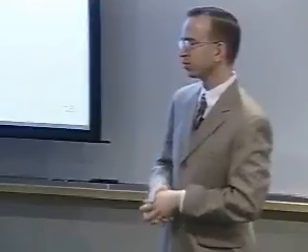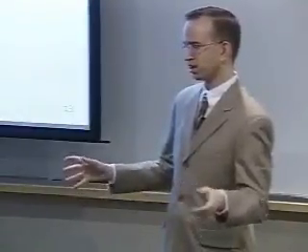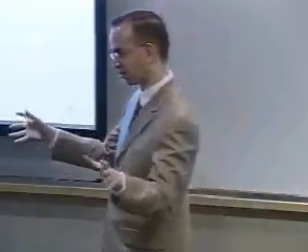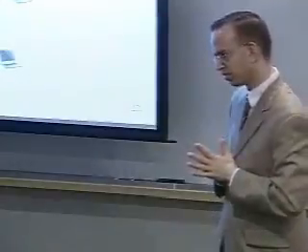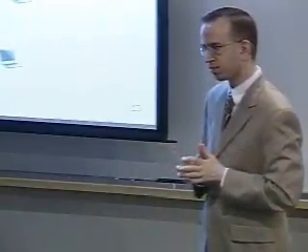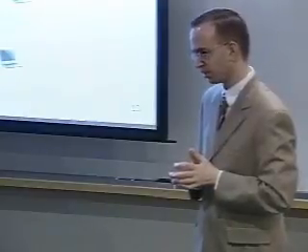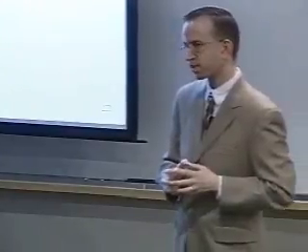So through our device, we completely control the signal. So you can view us as sort of, we can play God, if you will, with these signals to some degree. But you have to decide how the power attenuates if you want to emulate longer distances. Right? So we do decide how the power attenuates. That's correct. So, I mean, you are, in some sense, making assumptions about reception range and interference ranges.